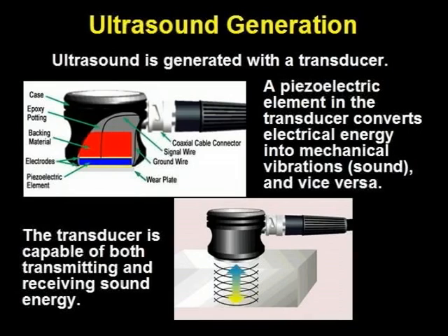A typical transducer has a piezoelectric element with a conductive electrode on opposite faces. The outside face is grounded and the voltage is applied to the inside face. A backing material is used to dampen the vibrations and tune the response to a specific range of frequencies. The outside face may be protected with a wear plate for manual contact inspection, or be fitted with a wedge to generate a refracted, mode-converted wave, or with a shaped face to focus sound for immersion testing.